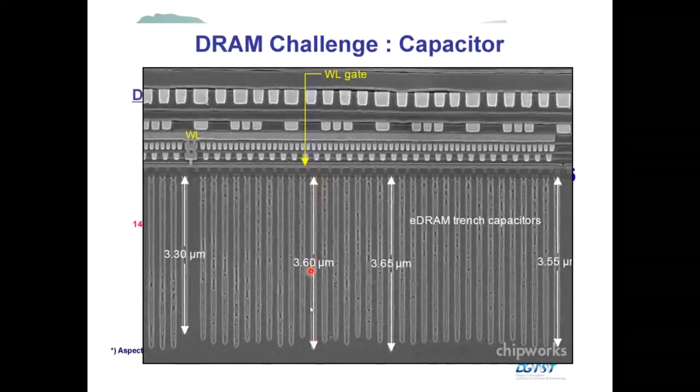This is a 3 micro something, and this small length is a tenth of a nanometer. So this is the single cell of your DRAM. You can store 1 bit in this capacitor, and you should make billions of these. For 1 gigabit RAM, you should make 10 to the 9 capacitors, and they should all be working.